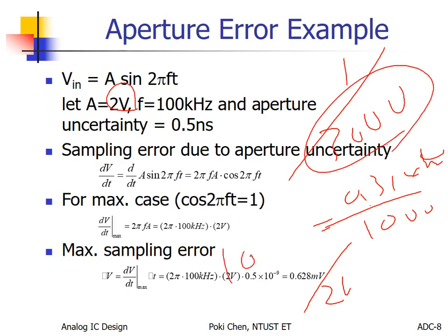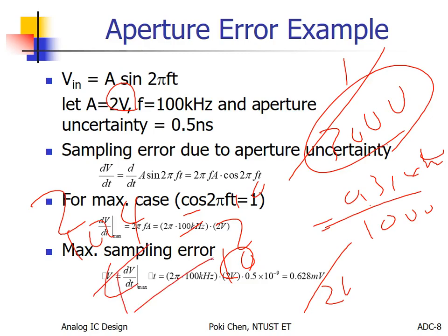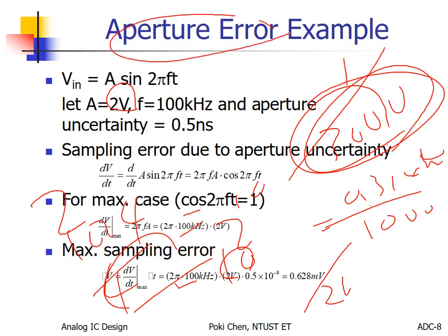For 10 bits, it is, right? 11 bit, 2000 something, 12 bit, 4000 something, right? So even if your ADC is perfect, I need to warn you, according to such an actual error, the real effective number of bits will be less than 12.